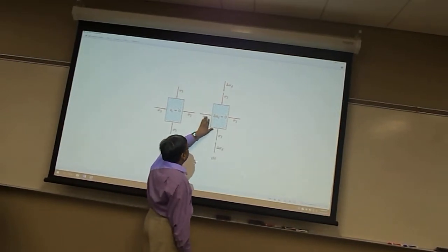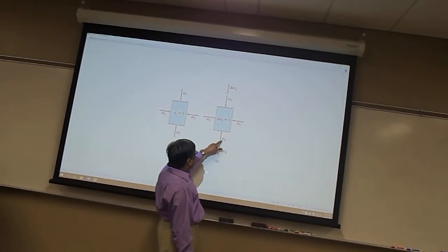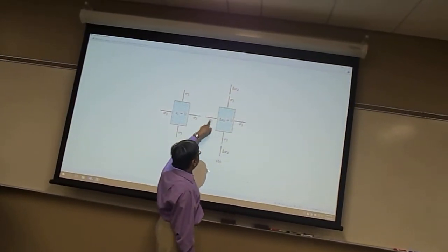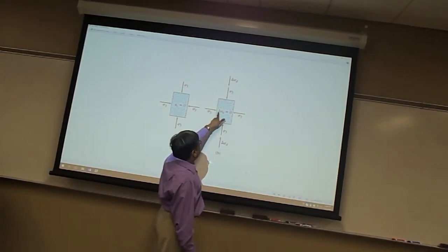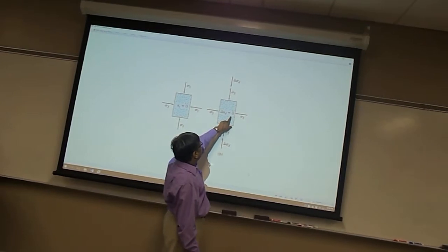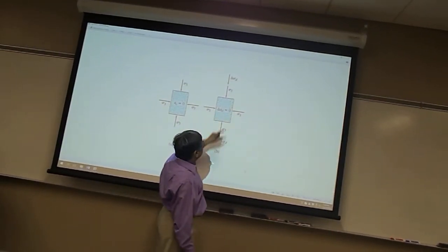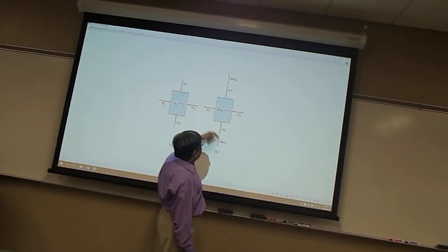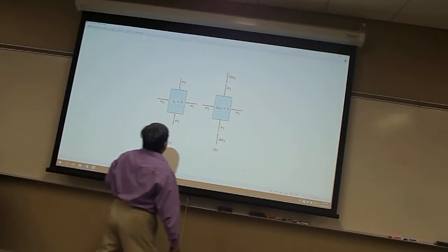We apply this deviator stress to increase the vertical stress from sigma 3 to sigma 1. Sigma 1 is the sum of these two things, and we apply this so slowly that we do not allow the pore water pressure to increase from 0. Because pore water pressure is 0, we get sigma 1 equals sigma 1 prime, sigma 3 equals sigma 3 prime.